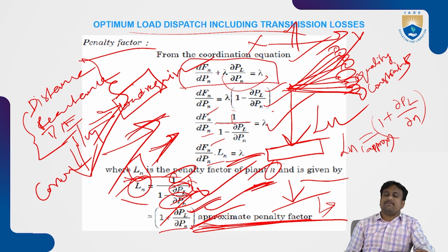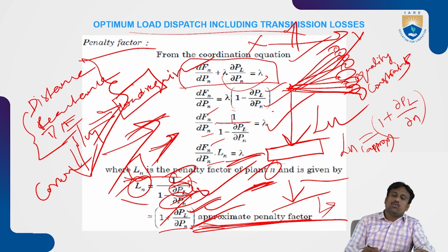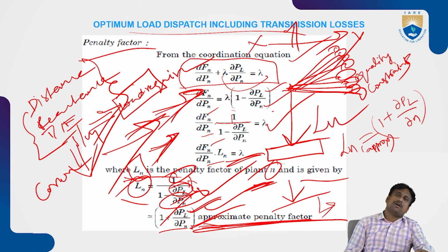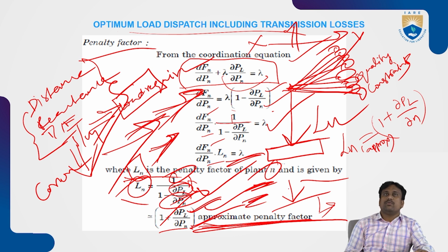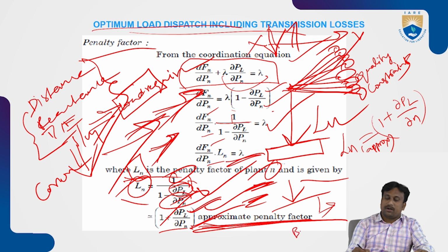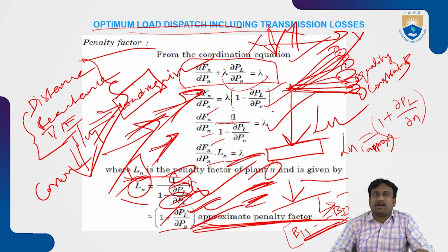If we exclude the transmission losses, we cannot define the suitable condition of the load requirement for n number of generators or n number of units. This is the reason we should go with the optimal load dispatch with the consideration of the transmission loss coefficient. These are suitably fulfilled by the B coefficients. We already derived them in terms of B11, B12, B33 in a matrix formation. These will coincide with the Lagrange's coefficient, and they give better results in defining the cases.